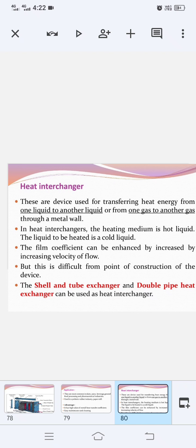Now let us learn about baffles. What are baffles? They consist of a circular disc of sheet metal with one side cut away. These are perforated devices to receive the tubes. To minimize the leakage, the clearance between the baffles, shell and tubes should be small. Baffles are supported by one or more guide rods which are fastened between the tube sheets by set screws. These baffles are placed outside the tubes and they increase the velocity of the liquid outside the tube.